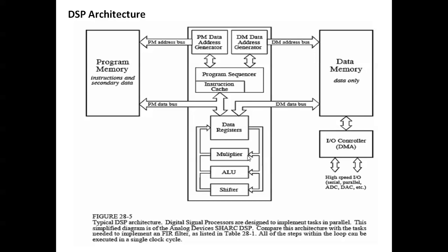So direct memory access means that without interruption of the CPU, we can directly access the memory. That means the CPU has some other work, but if you ask the CPU, then the CPU will have to help to get the data. It will take time, and the processing is more. So avoiding that, we can access the memory data, that is the DMA controller, without the help of the CPU.